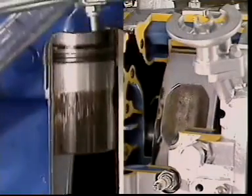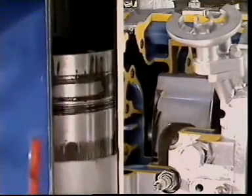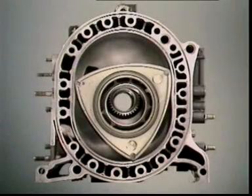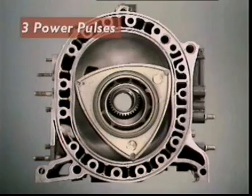How does the output of one rotor compare with the output of a piston engine? Look again at the working chamber. How many of these chambers are there in the housing? There are 3. 3 working chambers between the rotor and housing, and 3 lobes on the rotor. This means that for each complete rotation of the rotor, there are 3 power pulses.